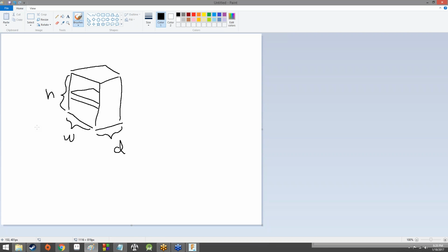Yours isn't doing it either. I'm not entirely sure. Just try and go through the same thing with making sure you're clicking on one of the lines and you're just clicking once. Make sure you're in sketch mode. Maybe hit escape a couple of times to get out of sketch mode, and then try going back into it again, and I can show you how to do that in a sec.